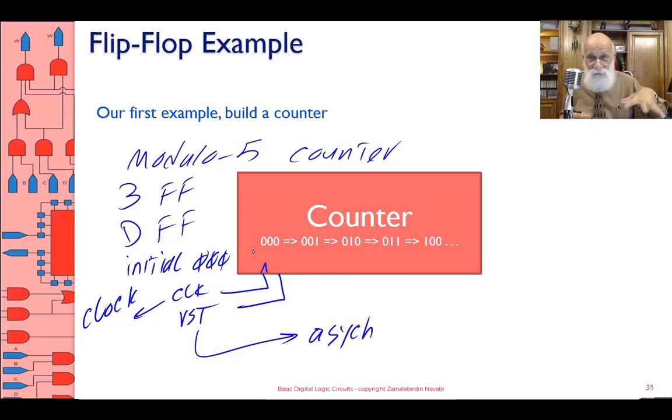Okay, that is not in the definition of the problem. The definition of the problem says this is a counter, and then at the end, when you use a flip-flop with the positive edge flip-flop, this definition becomes a rising edge counter. Okay, so what I'm saying now is you don't really have to worry about the type of flip-flop that you're using at this point.